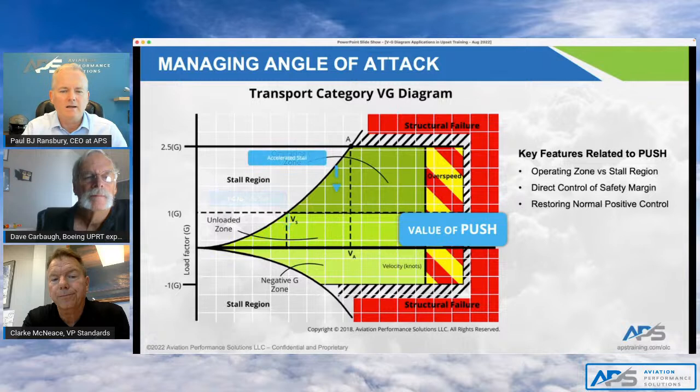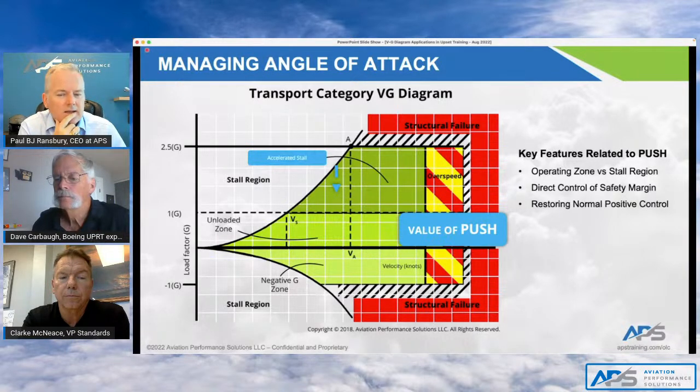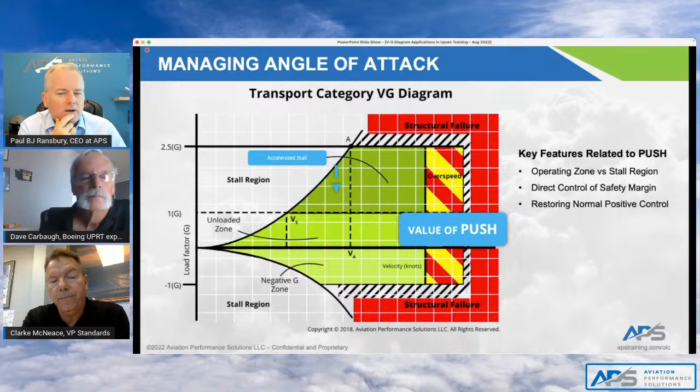Awesome. Absolutely. Okay. Let's move on to an accelerated stall, because that is analogous, although the speeds would be different. The load is different in this particular case, in that now we move up the curve a little bit. So in this situation, lift limited in this scenario. But here's an example of where our textbook clean VS speed, our stall speed, very quickly goes to a different speed. And we can see here that it's a much higher speed. Same thing, we want to reattach the airflow by unloading the airplane. And very often this occurs in a circle to land approach, over aggressive with the airplane, maneuvering at high altitude with inappropriate bank angle. This can appear for a number of reasons, but the characteristic push to reattach the airflow is critical.